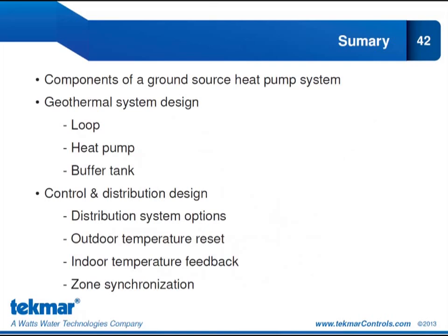We looked at the control features of outdoor temperature reset and indoor temperature feedback, and how those two control features can be used to lower the entering load water temperature whenever possible. And the lower temperature we have, the higher efficiency we have. So it's in our best interests to try to lower that ELWT whenever we can, and those two features allow us to do that.